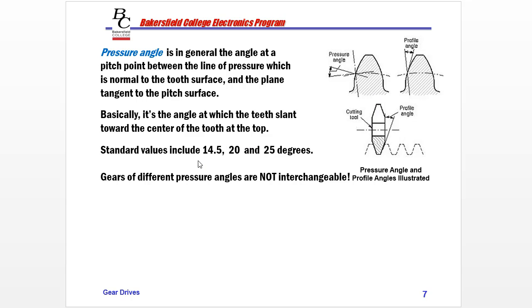It is important to know the pressure angle because gears of different pressure angles are not interchangeable. The gear teeth will not mesh properly and it will cause damage. If the pressure angle is greater, then the meshing is going to be harsh.